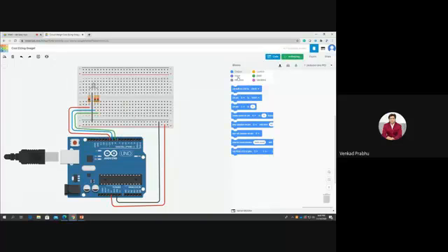For that you can see some options here: output, input. One minute, it's still running. Okay, so here just go to set pin number, drag it and put it in the work area on the right side. So first I want the red color to turn on, so set pin number, just drag that. Red is connected to pin number 10. You can see it in this diagram. Red I have given to pin number 10. So pin 10 to high means red color will be on.